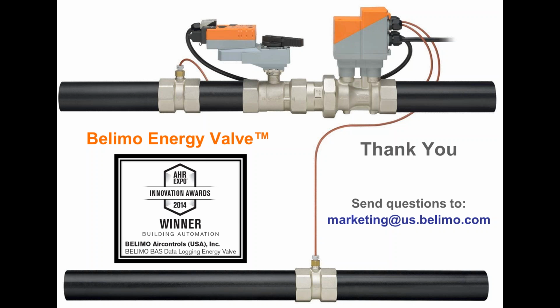Now, all Belimo catalogs contain a chart that will show you, let's say you buy that 2-inch valve, but you're only going to run it at 45 gallons a minute. Well, there's a chart in there that will tell you how much pressure is required to achieve 45 gallons a minute through that valve. So as you do your pump calculations, you're going to want to consider which valve is sort of your critical one, which one you're sizing your pump based on, and then take a look at the specifics. But the short answer is if you size around 5 psi, you're done, but you can do a little better than that if you want to dig down into it.